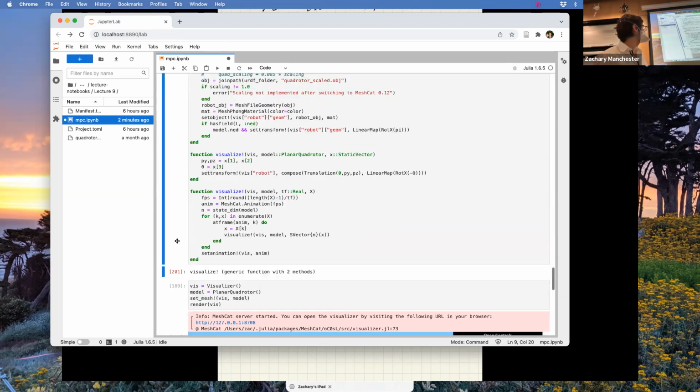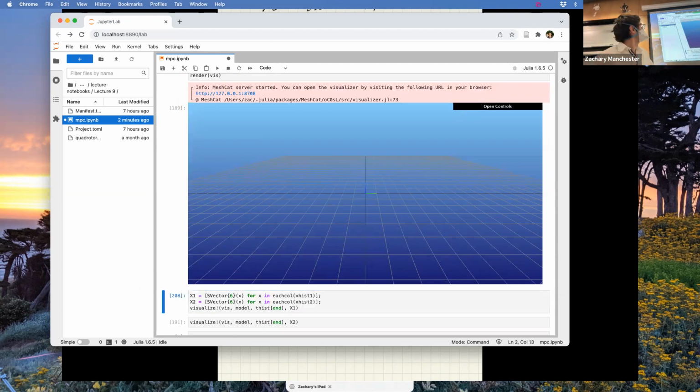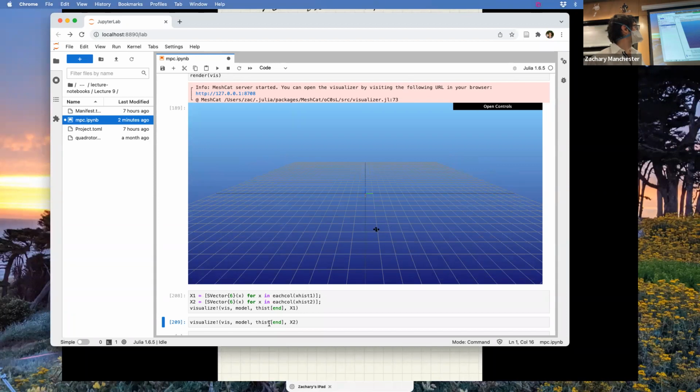Let's actually go visualize a little bit what it's doing. Oh, I shouldn't have done that. That's the LQR just barfing. So here's the MPC controller. It starts way out there, and it does some crazy stuff, but it's still stable. It doesn't crash. In particular, it's taking a huge bank right out the gate, and it's going through the floor, which is maybe bad, right? So a pretty obvious next move would be to put in a state constraint that says the height has to stay above the floor, which you're going to do on the next homework, and play around with that.